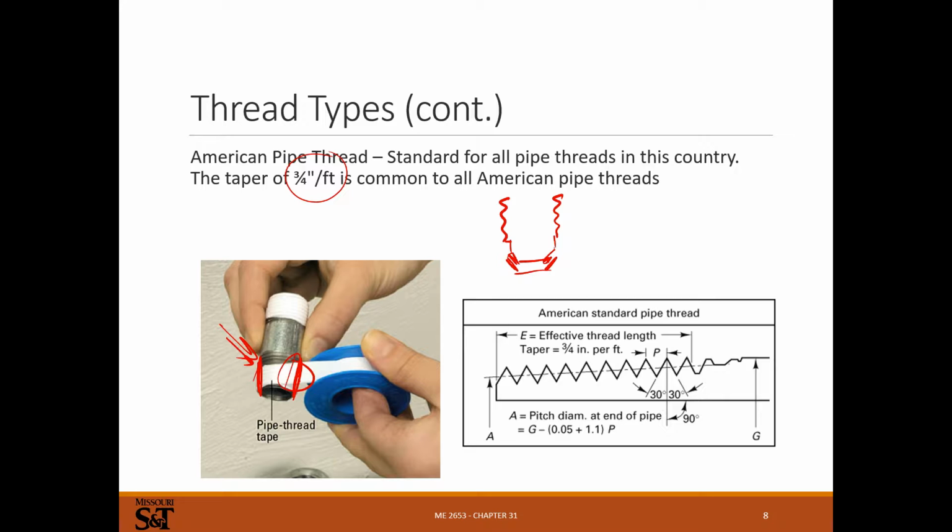You can tap these things in the field, and you can get fittings that already have the taper on it, and you can get just a blank steel pipe, and with a threading die machine, a thread cutting machine, you can cut the tapered threads on it, and then just with a pipe wrench and some Teflon tape, tighten these things up. I'm not sure of metric tapered thread standards.